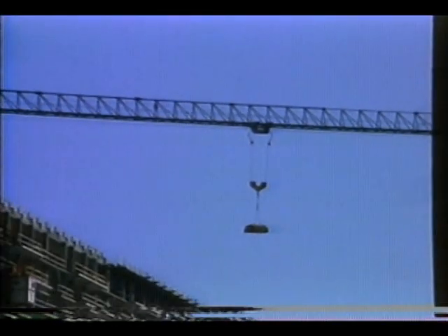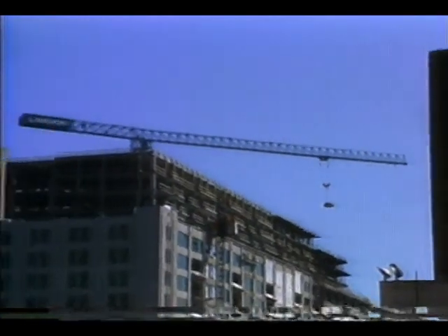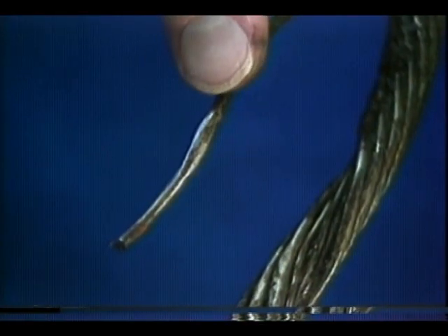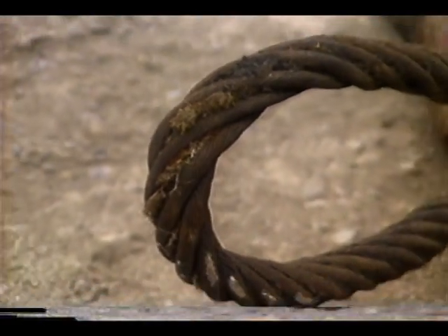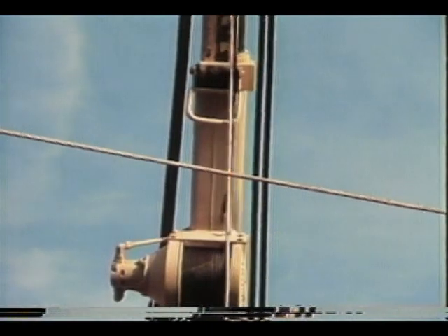Only inspection can detect potential hazards and reduce accidents. Construction regulations under the Occupational Health and Safety Act state that steel wire rope must not be used where 6 randomly distributed wires are broken in one rope lay, or 3 or more wires are broken in one strand in any rope lay, where wear exceeds 1/3 of the original diameter of outside wires, where there is kinking, bird caging, corrosion, or any other damage resulting in distortion of the rope structure, or where there is evidence of any other possible cause of rope failure, including contact with electricity.